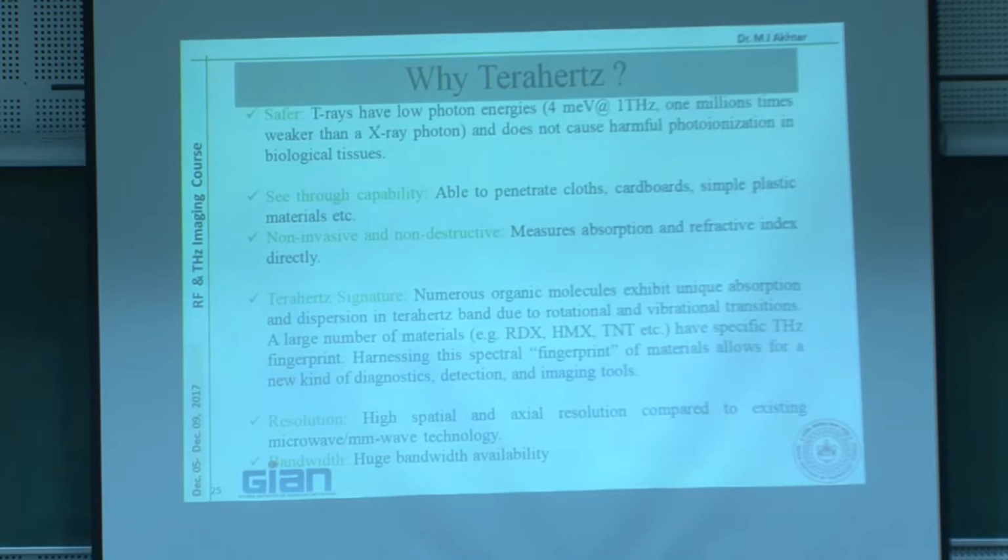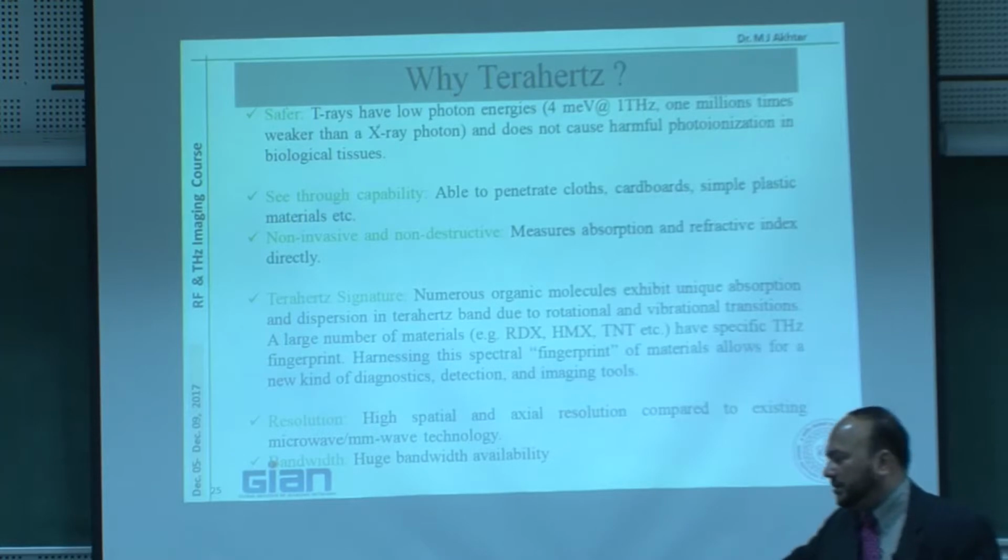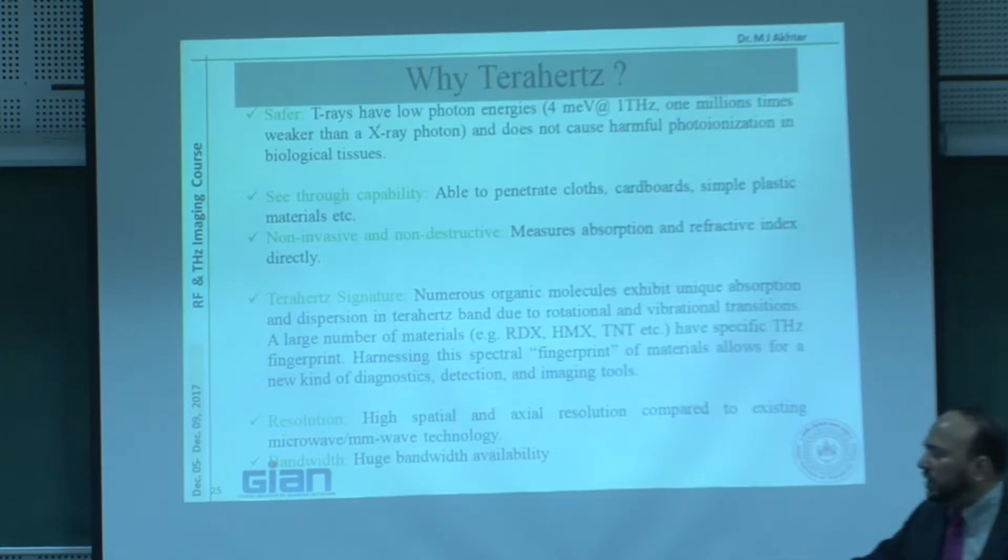The same way as millimeter wave, terahertz is one step ahead, provided that you can justify the cost. Terahertz will have better resolution, and although it has high loss in moisture, for anything in clothes, unless you are fully wet, it is fine. It can penetrate the clothes, and even a plastic board. Even this box, which is just a very thin thing and not glossy, I can use terahertz to see what is inside. So that application works. There is no doubt about this.